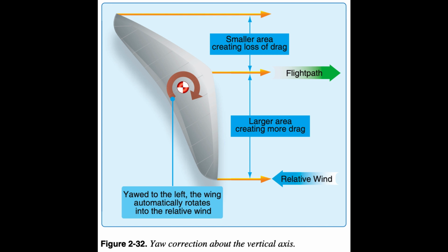There is a slight amount of adverse yaw similar to an airplane that can be noticed when a roll is first initiated. The amount varies with the specific manufacturer's design and make/model. In addition, the wing can yaw side to side to some degree, with some different manufacturers' make/models more than others. The higher performance wings with less twist and a greater nose angle are noted for less yaw stability to gain performance. These wings also require more pilot input and skill to minimize yaw instability through pitch input.